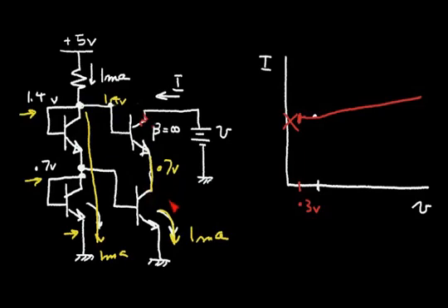So the key thing is that the operating point on this transistor is not going to change very much. I can change this voltage here quite a bit, but the operating point on this transistor that controls the current doesn't change much. So in this case, the current will be very flat. It won't have this high slope here, but my operating voltage will be not as good.